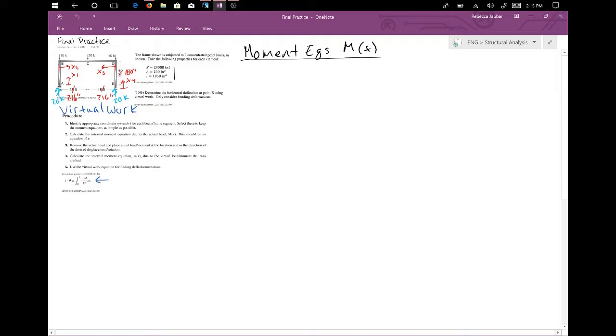If not, I really recommend brushing up on your definitions for internal forces. But anyway, so our first real moment equation, you'll understand why I'm saying real in a second, will be 0. And the bounds will, not that it matters because it's 0, but just to be good practice, be from 0 to 180. So let's go to the next moment equation, which will be for x2. I recommend, if we're going to draw this, that we draw the whole frame. We'll just draw a little simple frame here.